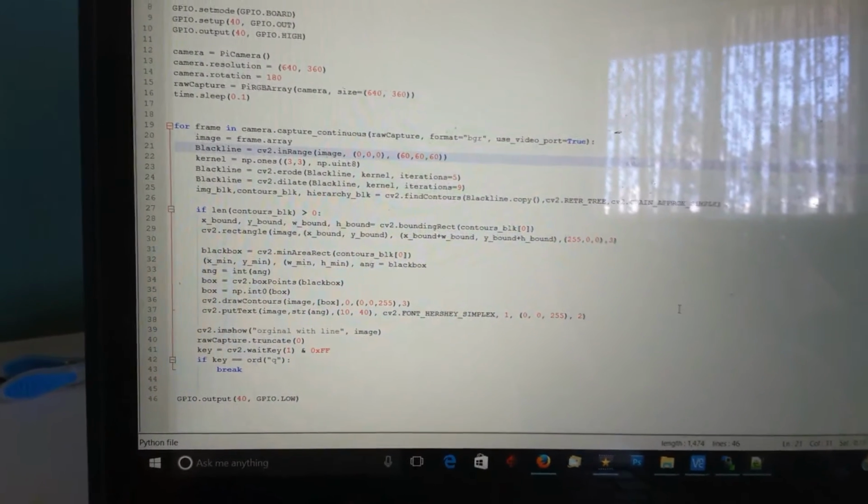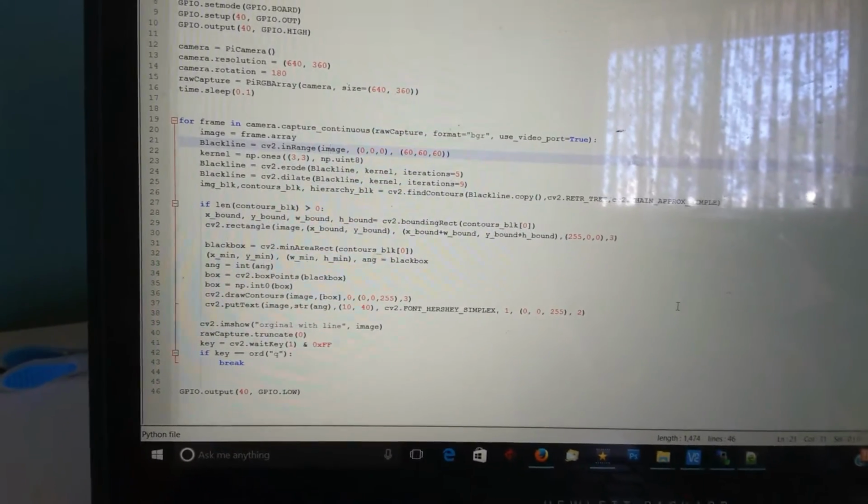The other thing that this does is as I'm coming up to a corner, before I get to the corner, it starts to angle out and tell me that the future trend of the corner is to go out that way. And that allows the robot to cut the corner a little bit in order to get a little bit better speed and efficiency. Okay, so now let's look at some code in order to do that.